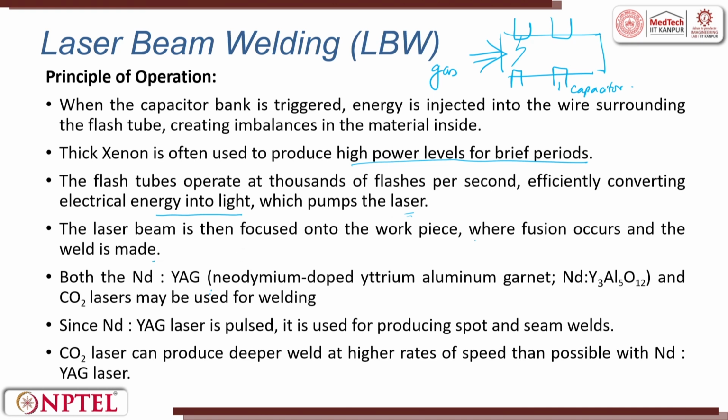Both Nd:YAG laser and CO2 laser may be used for welding. CO2 laser is gaseous welding, solid state welding is Nd:YAG laser. Since Nd:YAG is pulsed, it is used for producing spot and seam welds. CO2 is continuous. So, why are they talking about pulse and continuous? A pulsed laser has very high energy density, because pulsed means you are trying to pulsate.